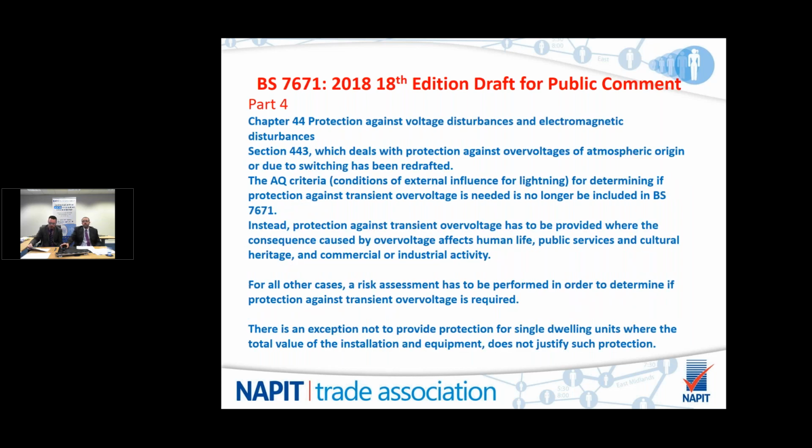Chapter 44, protection against voltage disturbances and electromagnetic disturbances. Section 443, which deals with protection against overvoltages of atmospheric origin or switching, has all been redrafted. The AQ criteria, which are conditions of external influence for lightning, determining if protection against transient overvoltage is needed, are no longer included in BS 7671.